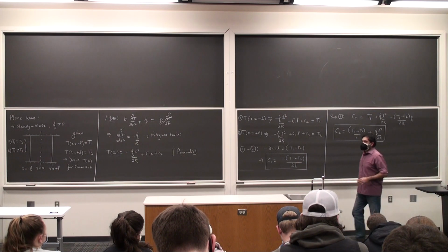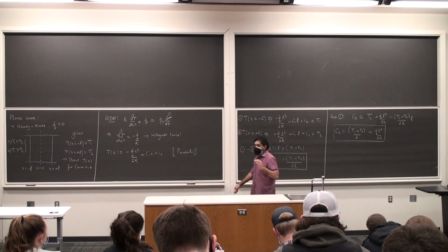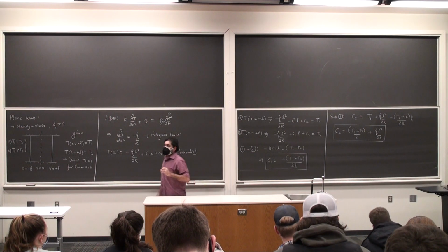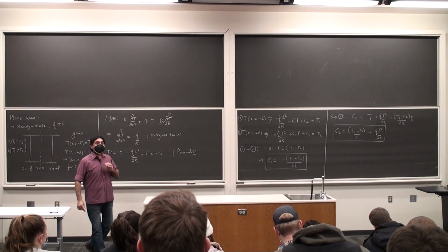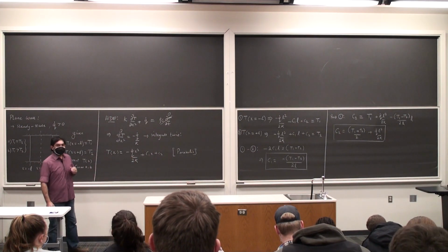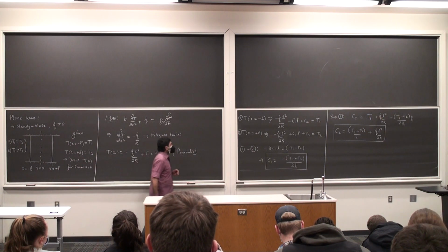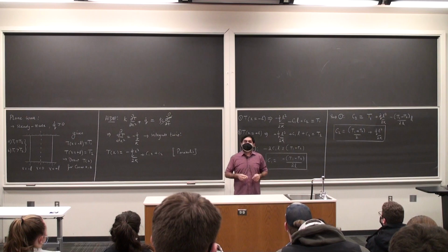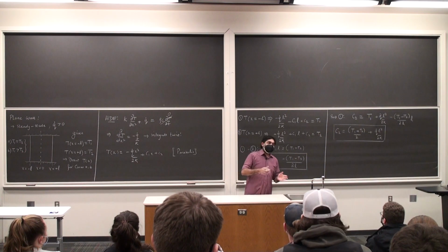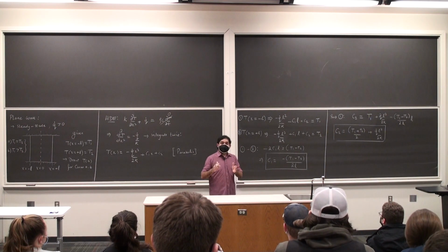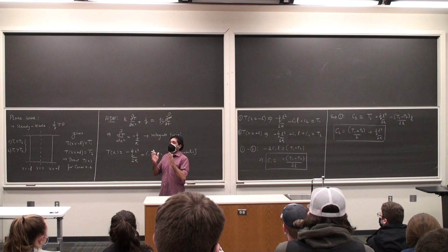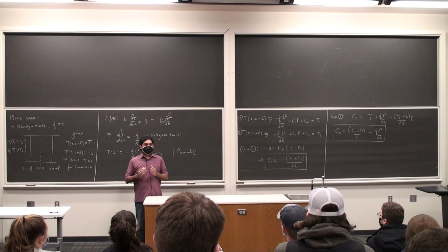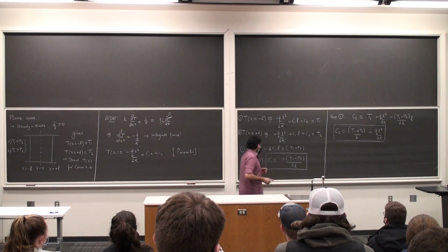Once again, we have done this with actual numerical values. Now we don't use values. These are the best type of problems where there are no numbers present. Okay, this is where thinking is involved. I take C1, I take C2, plug it back into T of x, I get my temperature profile. I take the first derivative, I get the slope. The slope of the temperature profile tells me the magnitude of the conduction flux. Okay, for a plane wall in this situation.